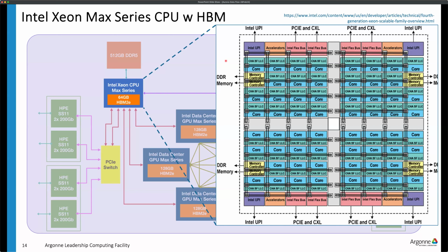And then I think the last question is, do CPU and GPUs have cache coherency to enable zero copy? Cache coherency between the CPU and GPU is a bit of a question, because there is cost associated with it. They are physically distant, right? So in virtual cases and software libraries, you can claim there's cache coherency, but you are going to go through a PCIe link, right?